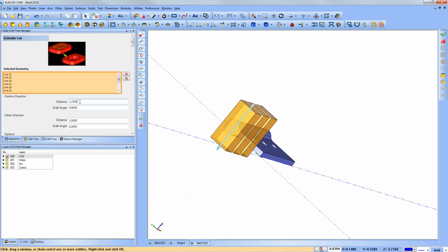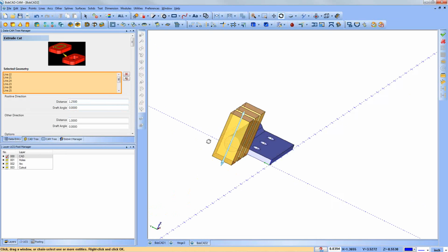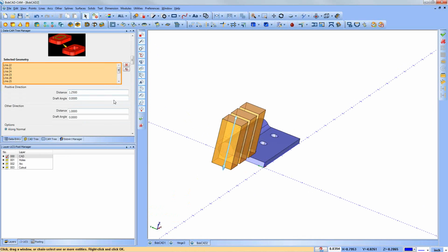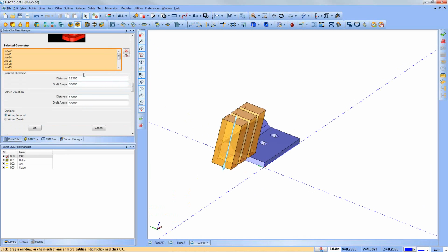If you want to add a small allowance, or you have a number that's not exactly rounded, I'll use that a lot. Like a plus 40 thou, 20 thou, it's convenient. I use it like that in the CAM a lot, but you can use that in any of our input boxes.